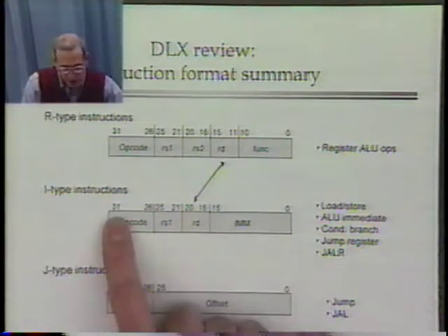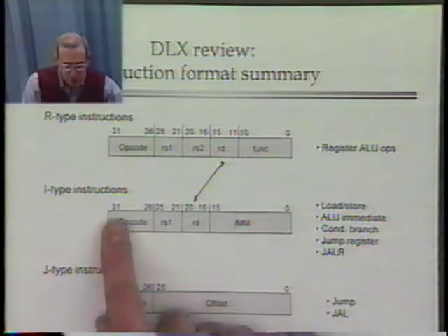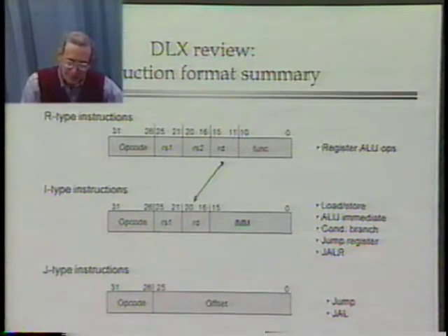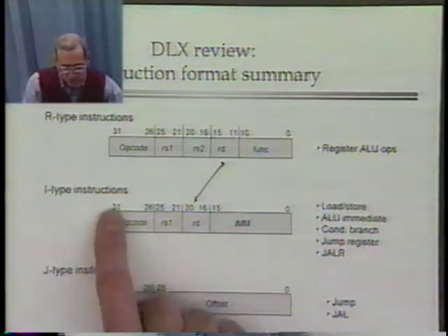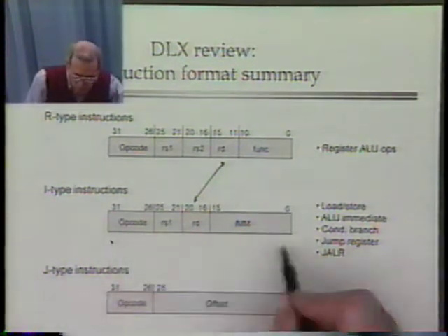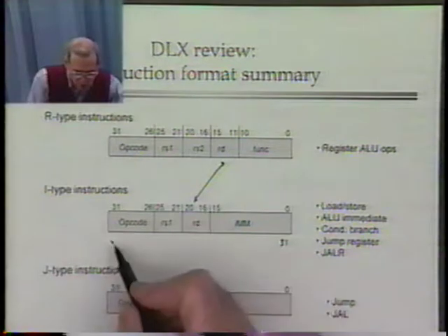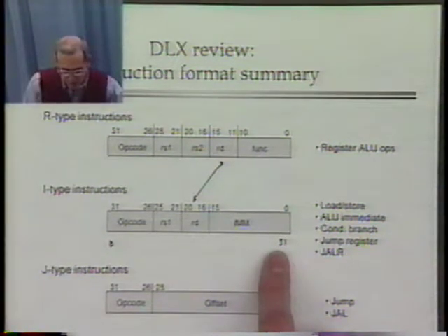The other thing I might point out is that bit numbering within a word for instructions is another one of these issues like little endian versus big endian, which basically doesn't matter, and unfortunately people have done in different ways. About half the current RISC processors number bits this way, half the current RISC processors number them from 0 to 31 in that direction. The book, in fact, is inconsistent. I found places where it does one and other places where it does the other.